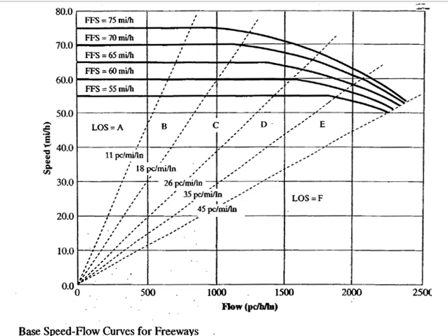These are some of the graphs which are plotted for fixed values. They assumed some values of free flow speed and A and everything, and they plotted these graphs. You have to plot a graph like this for your highway in the template. So this starts with free flow speed, right? The starting point is what? Free flow speed. And what point is this? Breakpoint. From here to here, how do I get the point? I have to use the equation.